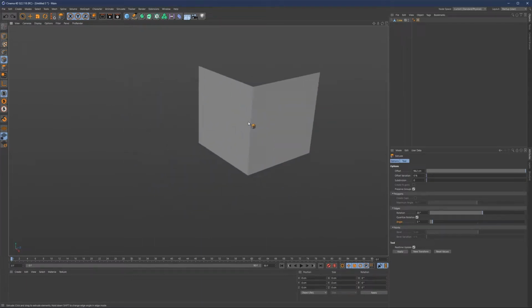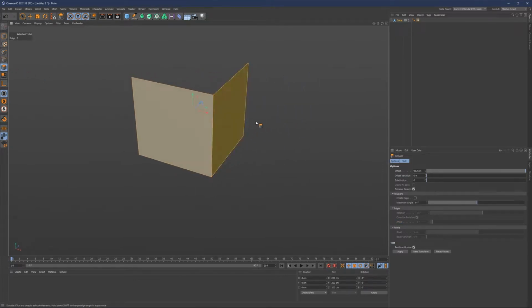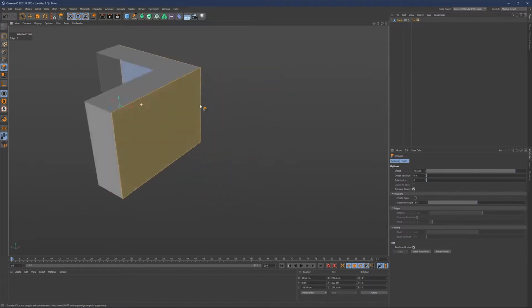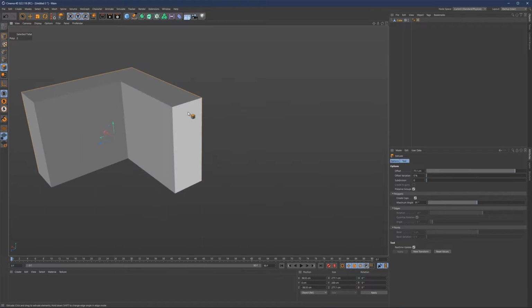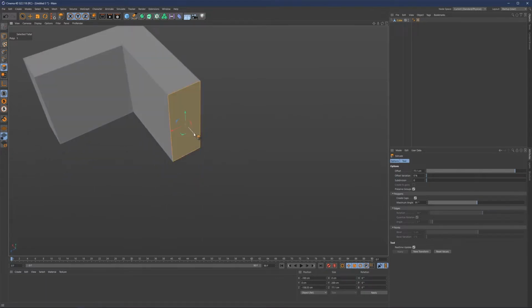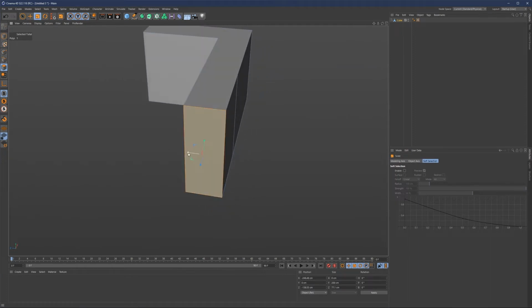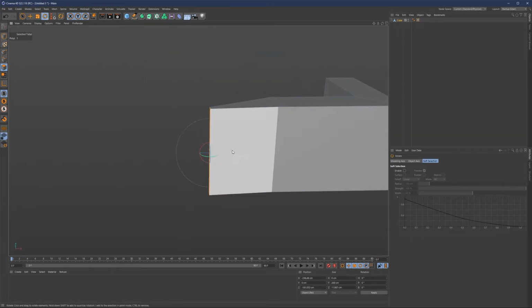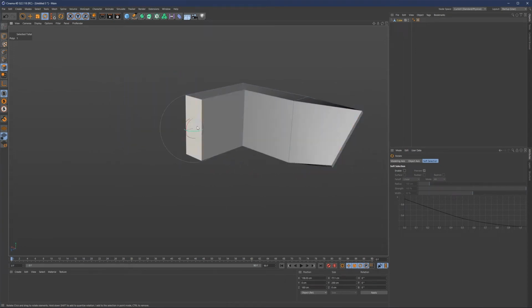All right, so just to summarize it one more time. We can now select two of these faces, hit D, we can extrude, we can now close caps. We can then, let's say, select this face, hold Control, extrude it here if you want to. We can use Scale if you wish to scale it a bit. We can use Move to move this maybe to the side. And if you wish, we can even rotate to give it more rotation. So this is, in general, how we're going to use Extrude.